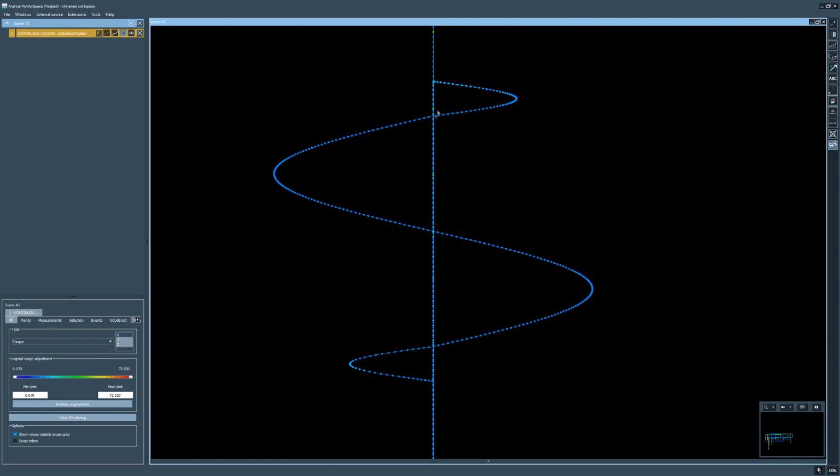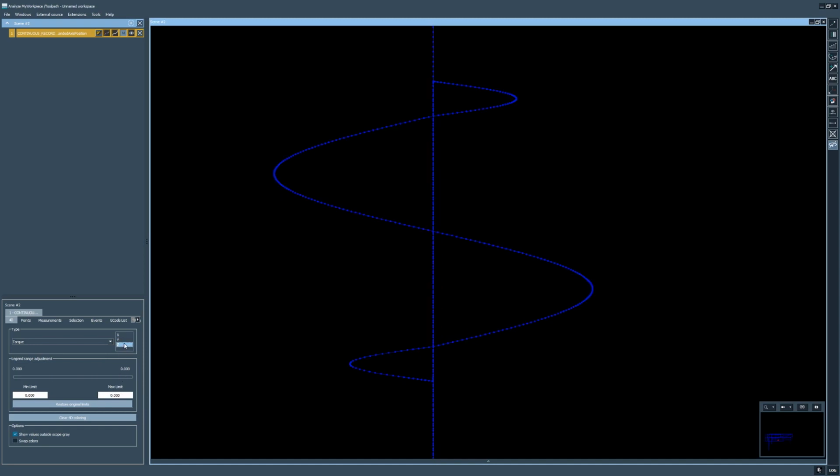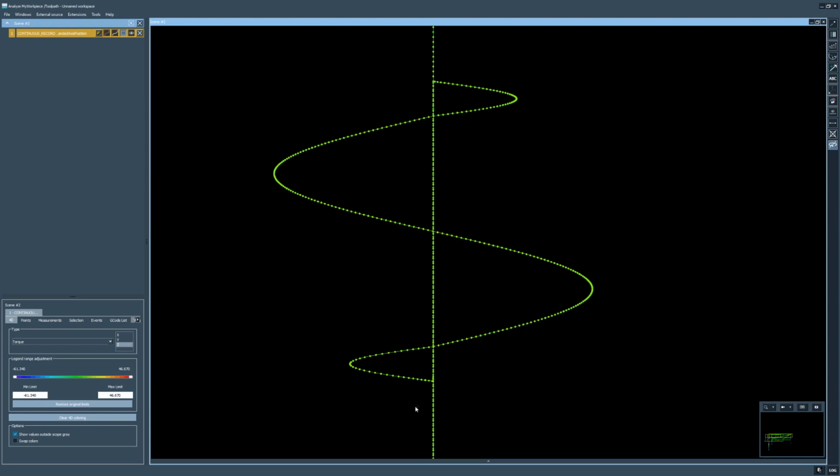That means we now see the torque vector only for the Y and C component. And if we reduce one more component like this, now only the C component is selected. So we should have selected at least one component. If we don't select anything, everything becomes blue. So let's just select the C component. What we now see is the color coding of the torque of the C1 axis. So this is now again a scalar field that we are seeing.